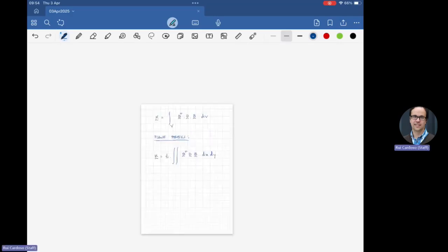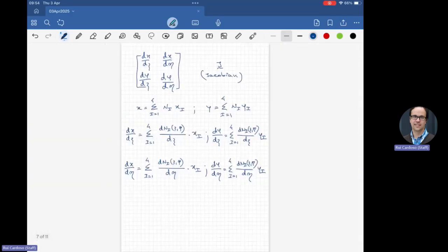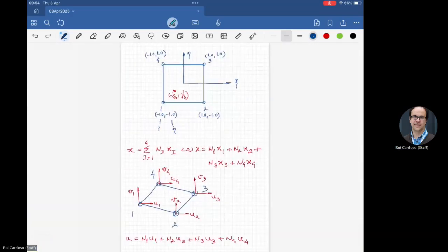I mean, if you think on this, let's go to the first slide. If you think on these two elements, one is a perfect element, always a square in the parametric domain, for which I always know the limits of that integral, right? Between -1 and +1, always. The one at the bottom is an element in the physical domain, which can be squeezed or distorted, very irregular shapes, different shapes every time, right? Imagine a mesh with 1 million elements. How many different shapes do you have there?